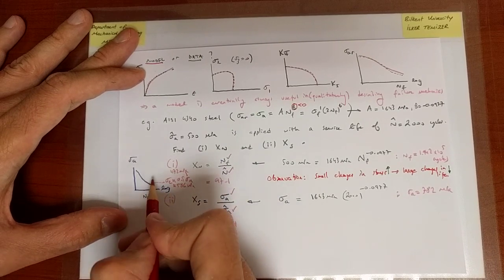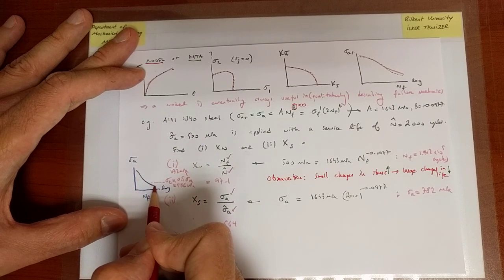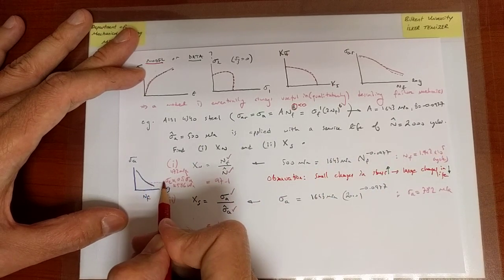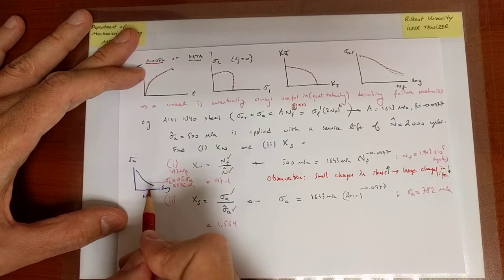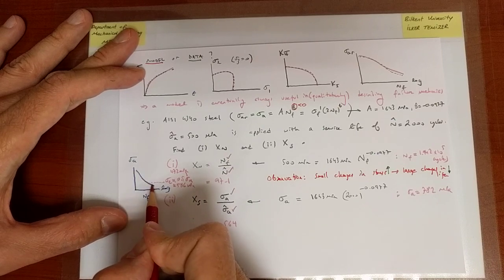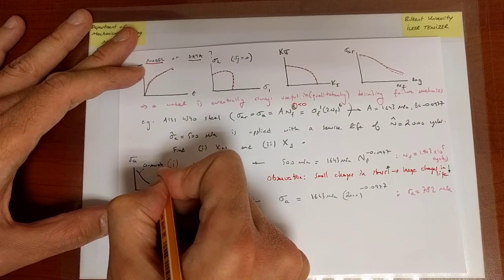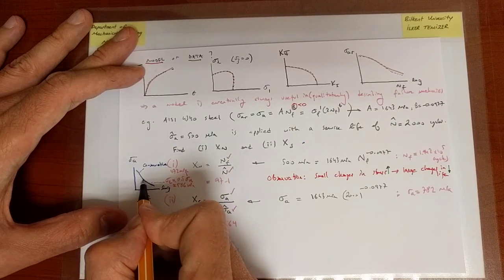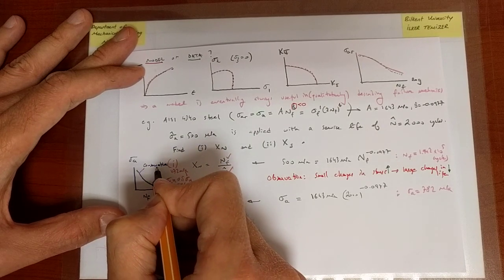So now, although the material might display an endurance limit, we're still predicting life through the blue line. In other words, for this given stress, we're saying that there's a certain life, and that life is this many cycles, whereas in practice the number of cycles might be very, very large. In fact, you might be able to cycle forever. So therefore, the blue line, notice, is always conservative with respect to the presence of an endurance limit. I don't know the data here, it's just a fit, but here it is conservative. So let us highlight that it is conservative in that region.